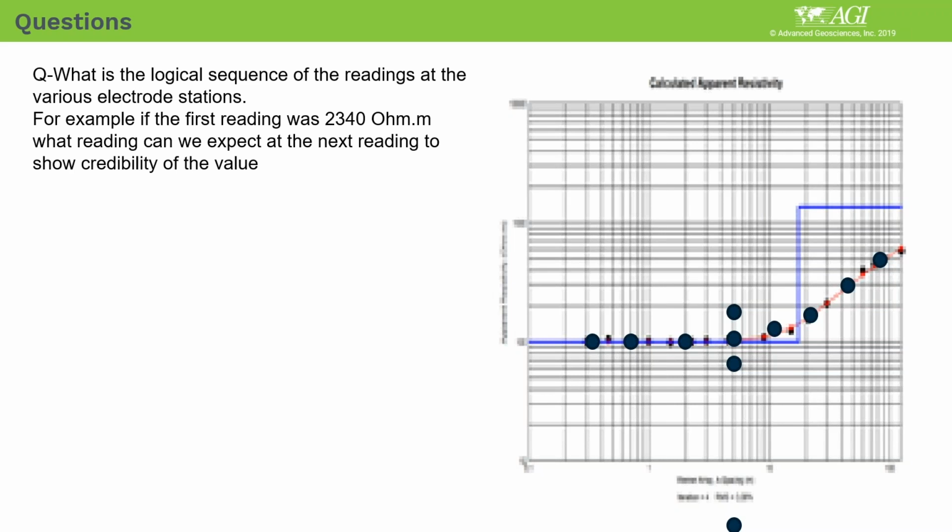Like if they say, okay, this is an ASTM requirement, you have to do Wenner, then you have to do it. But if you're doing geotechnical studies, groundwater studies, anything like that, the recommendation is dipole with multi-electrode measurements, which is faster and also gives better resolution.